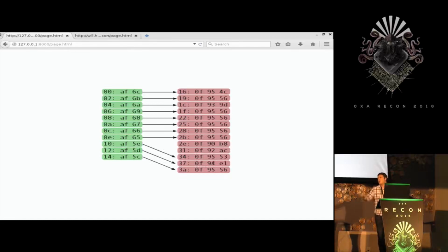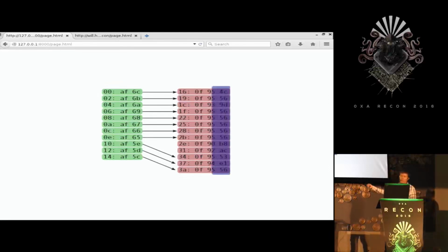It's one jump through another to get to the final destination that the first may not be able to reach. And if we look at the last few bytes on the absolute jump, we can start deciphering those as well. The lowest 12 bits all seem to differ, and they end up having address values that all point within the firmware module that we've loaded. They're all within the size bounds of what we're going to load. So this makes sense. It's a good sign we're on the right path.